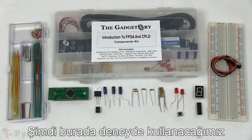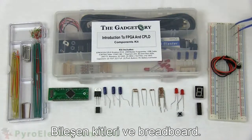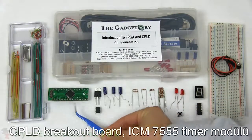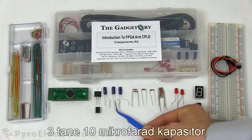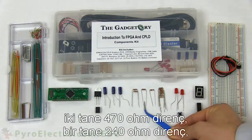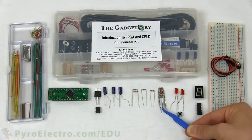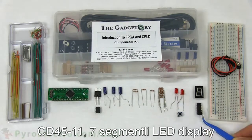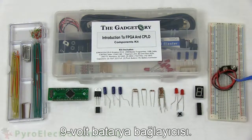Here are all the parts we'll be using in this experiment. The larger parts are a jumper wire kit, components kit, and a breadboard. The smaller parts from the components kit are a CPLD breakout board, ICM 7555 timer module, LM317 voltage regulator, 3 10 microfarad capacitors, 2 470 ohm resistors, a 240 ohm resistor, a 390 ohm resistor, 6 10 kilo ohm resistors, a push button, 2 red LEDs, a CD4511, a 7-segment LED display, and a 9-volt battery connector.